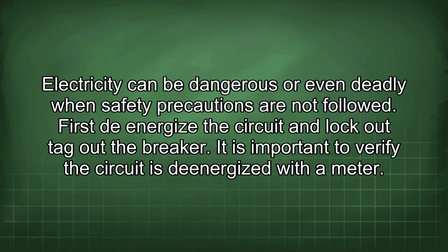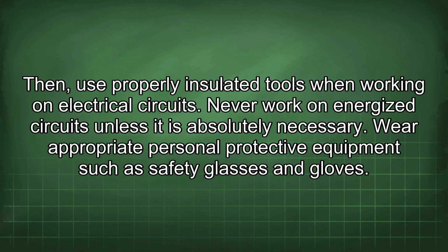First, de-energize the circuit and tag out the breaker. It is important to verify the circuit is de-energized with a meter. Then, use properly insulated tools when working on electrical circuits. Never work on energized circuits unless it is absolutely necessary.